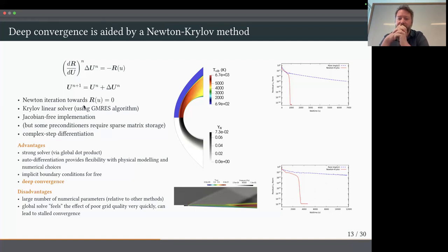So do I think the adjoint's a good approach? I guess to answer your question, if you're really worried and want to search the design space even more broadly, you might use a cheaper method to narrow down what is going to be the best, and then move to the higher fidelity method. So I guess that's a question about fidelity, where RANS is one level of fidelity, but you could go to panel methods for a really large, broad design space search.